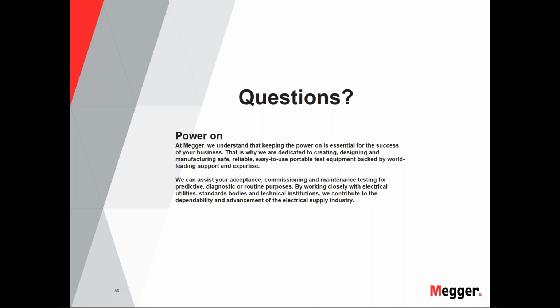It is not the usual practice, but some of the utilities do it in controlled scenarios. Sometimes it is risky to stop the prime mover power completely and then stop the generator power, basically setting up the excitation power. Sometimes it is over-excited. Also, it is possible it can go into the capacitive mode, basically called the leading mode. So that's a risk for the generator, but very well-controlled and very knowledgeable, well-trained people can do this process.